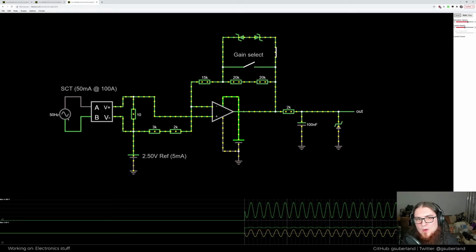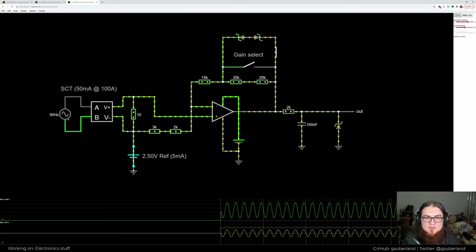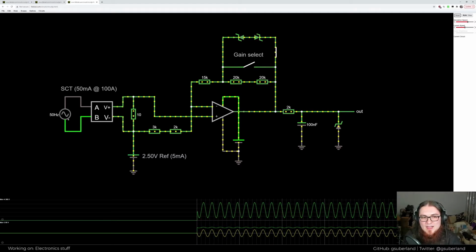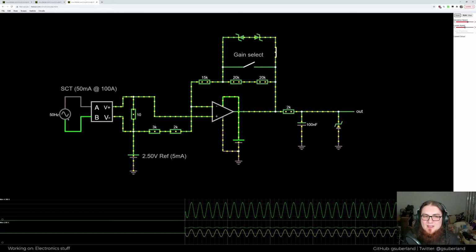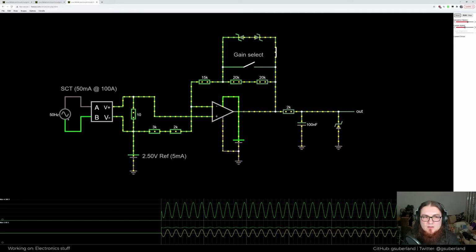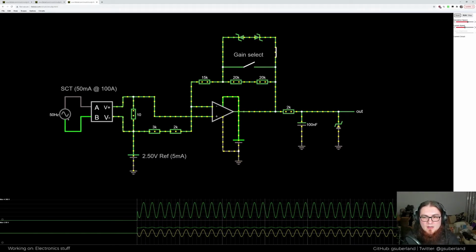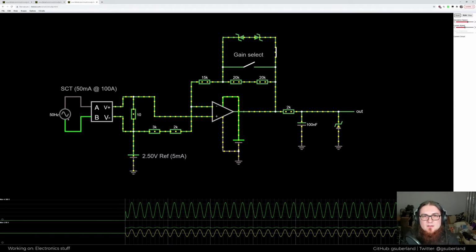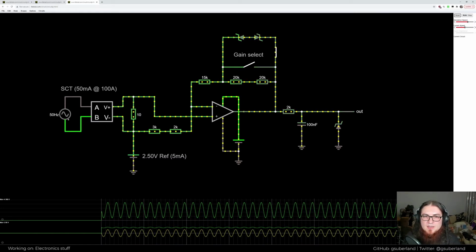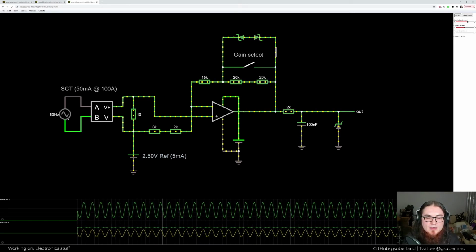Then, okay, yeah, it would be 12 times the amount of current than we actually need, which is still tons. But since we only have one supply here, the more current you start pulling through here, the more noise you generate because of all of the different signals being fed in at the same time. It starts to be more of a problem. The more overhead you have here, basically the lower impedance this whole pathway is, because you've got this high drive current, the less noise you get. So you start to get diminishing returns as you reduce these values, and you use more power. The circuit uses more power in total.